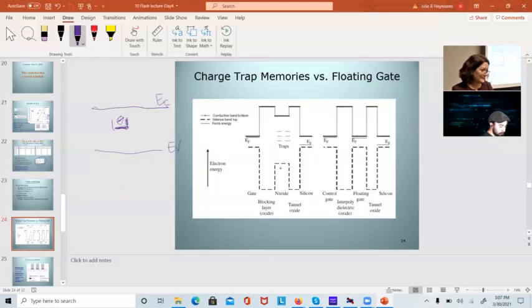Multiple seconds? Multiple seconds. Compared to the microseconds that ReRAM does? Yeah. Some of them have traps in the microseconds. It just depends upon what material it is, what conditions it's conducting under. So basically, you have to treat that electron in that trap like it's a random process, because you don't know when it's going to go off.